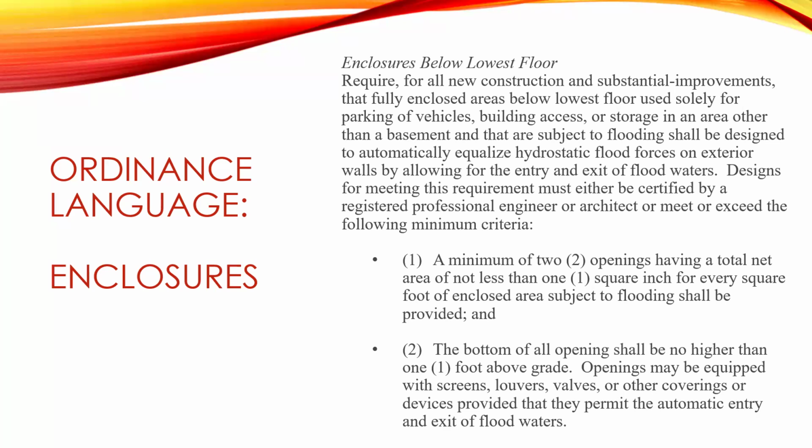And so they can also be equipped with screens or louvres, valves, but they have to be permanently disabled in the open position, or they're engineered openings that are designed to automatically open and close, so we can't have any human intervention needed for them to work. So yeah, and then that allows for, again, automatic entry and exit of floodwaters.